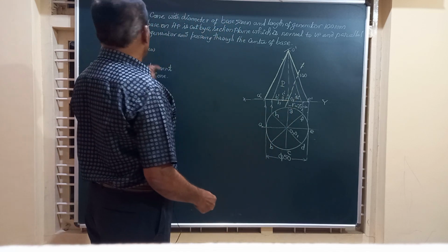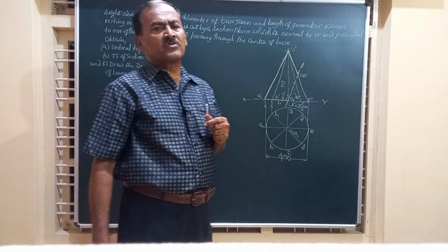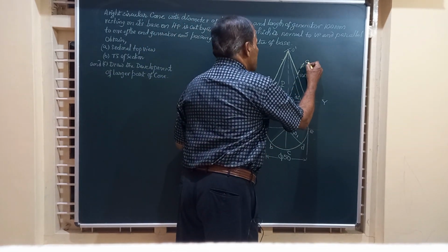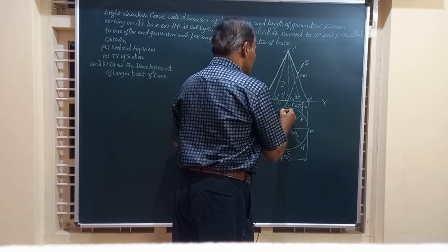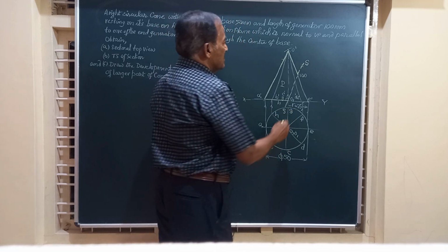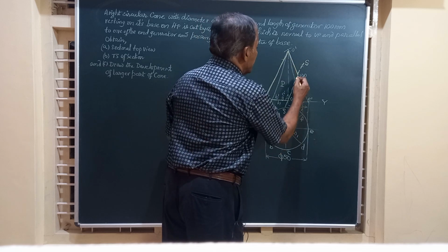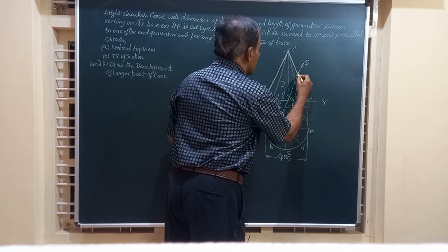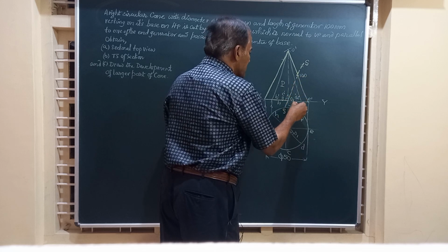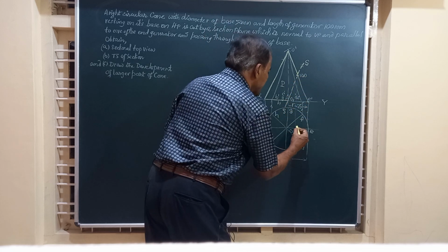First of all, let us draw this sectional top view. To draw the sectional top view, you have to see where this section plane SS is cutting the solid. Friends, you can see here, this O dash E dash is cut here. So you can draw a vertical line through that point and see it is cutting here.